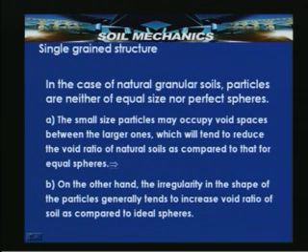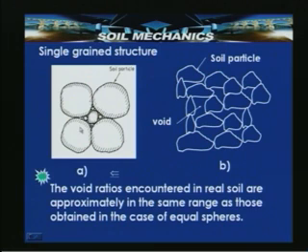Let us look into this aspect. Here it can be seen that between the large soil particles, the small particles of different soils get filled in and form the densest possible packing. So, this is one extent where the small particles get packed in between the large soil particles. This can yield the densest possible packing, which can yield minimum void ratio in the natural state.